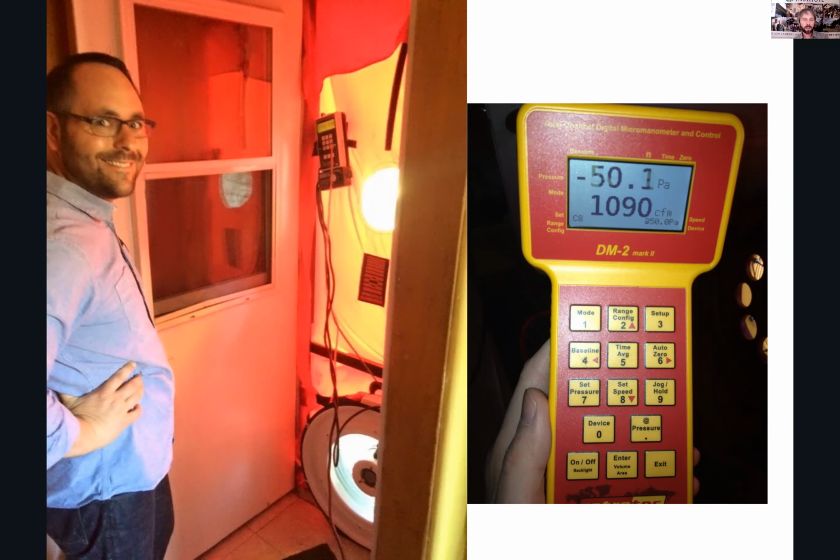Get an energy auditor in, have them set up a blower door test to depressurize the home or the building and give you a sense for how leaky it is. These tie to utility rebates and credits too. And you can have that blower door tester come in during various phases of the new construction project. And in some cases, it's required for code as well on new builds.